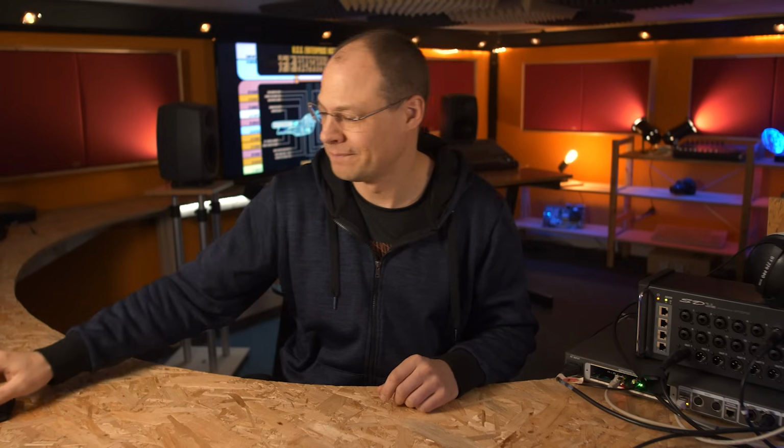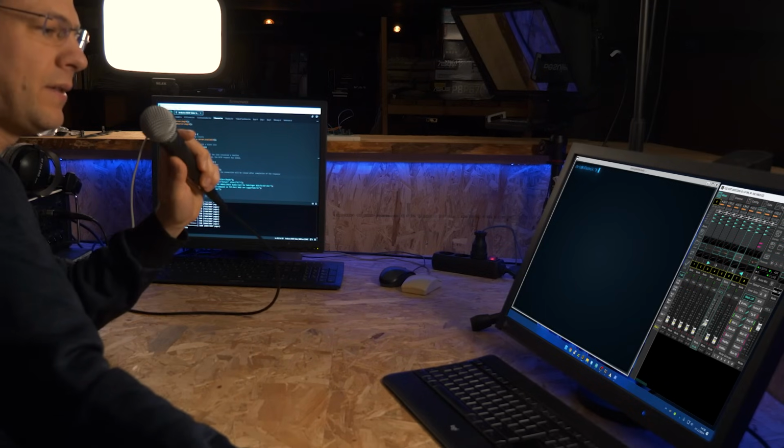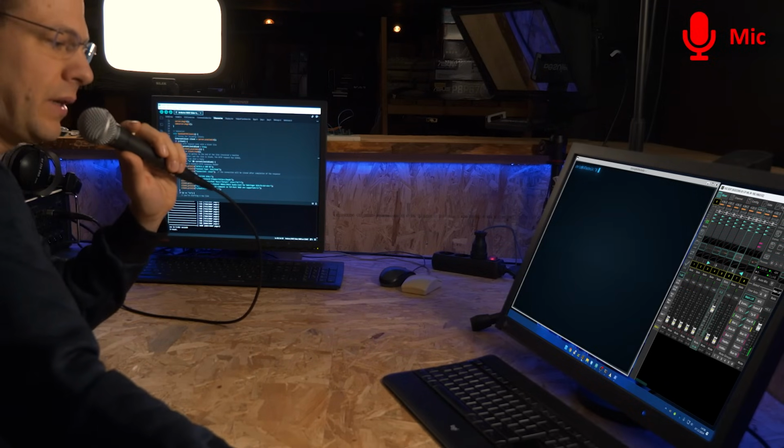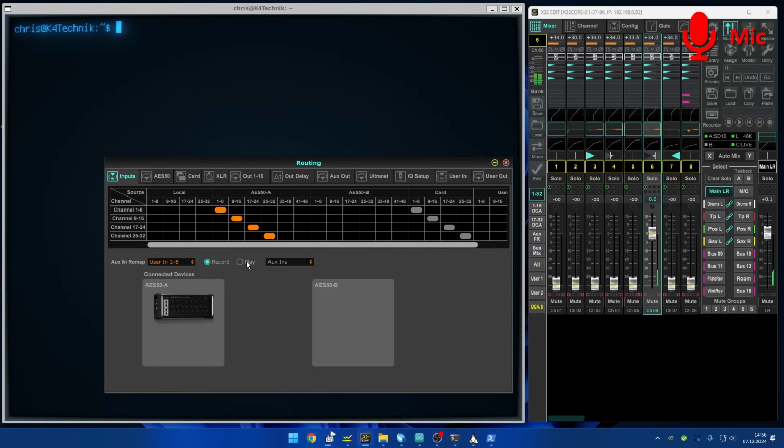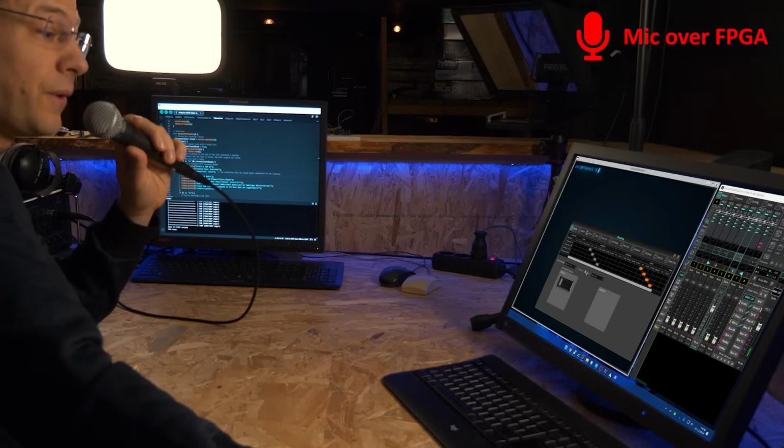To test the overall signal quality in my board I made, I will connect the input in my FPGA with the output directly to see if the serial data can pass through the FPGA without any problems. And if we then get clean signals, I have to work on the TDM decoder and encoder. So go to Quartus, recompile it with a feed forward of the TDM data and then see if it is working. Okay, the software is updated. I go to the X32, this is still working. Okay, and then enable play. And yes, it's working here. That's a good sign.